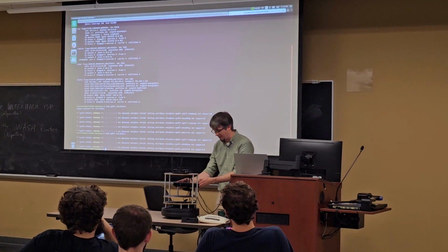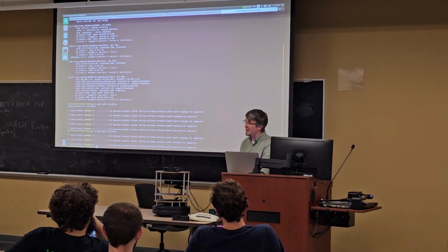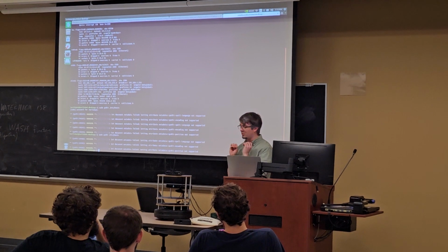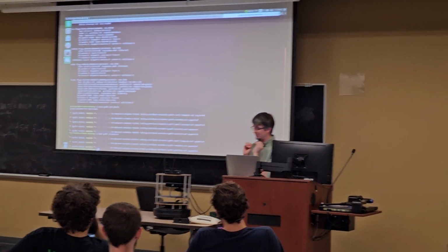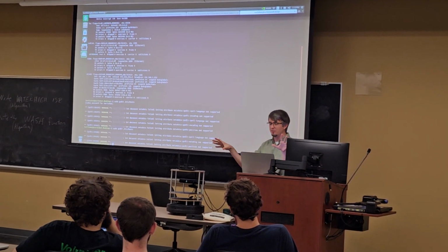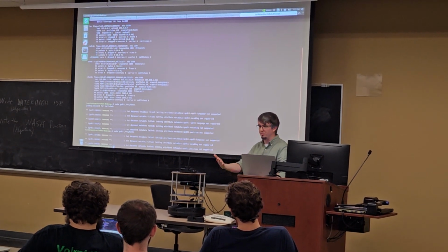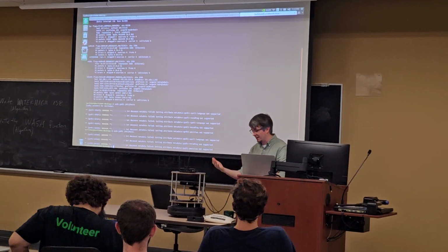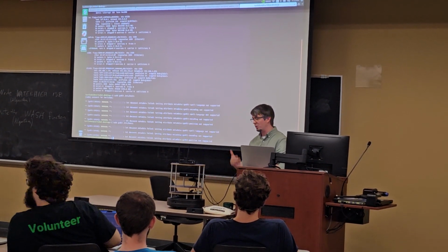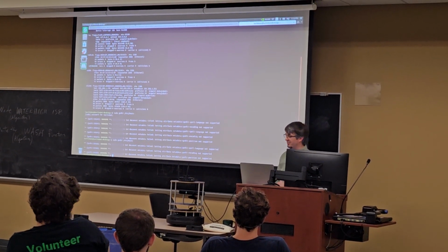And then I've also got an Xbox Kinect on the bottom here, which is its depth sensor. This is a camera that reads, basically there's a point cloud in infrared that is sprayed out in front of it, and the camera is looking for these infrared dots being projected into its environment. And then it's getting distance information. With that information, we can have the robot build maps of its environment and avoid collisions. And of course it's a camera as well, so you can recognize things in the environment.